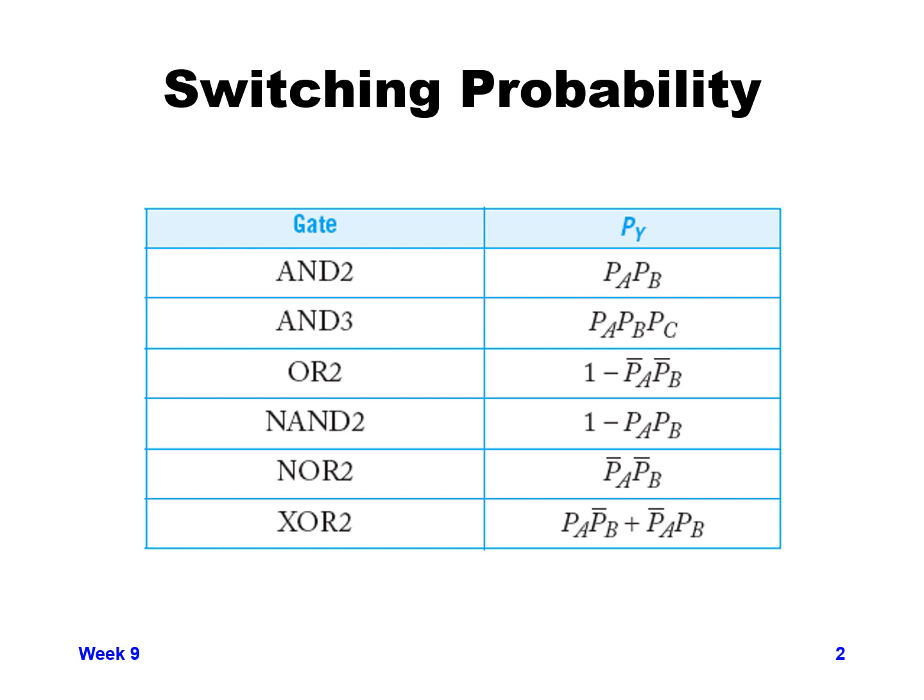Similarly, for an AND3, you have PA times PB times PC, and so the probability of the output being high for a 3-input AND gate is going to be, for random data coming in at 0.5 each, a factor of 1 over 8. 2 times 2 times 2 is going to give a 1 over 8 function. So the other gates, you can see the equations for those. It might be worth printing out this foil or copying down the probabilities for the other functions, for an OR function, NAND2, NOR2 function, etc.